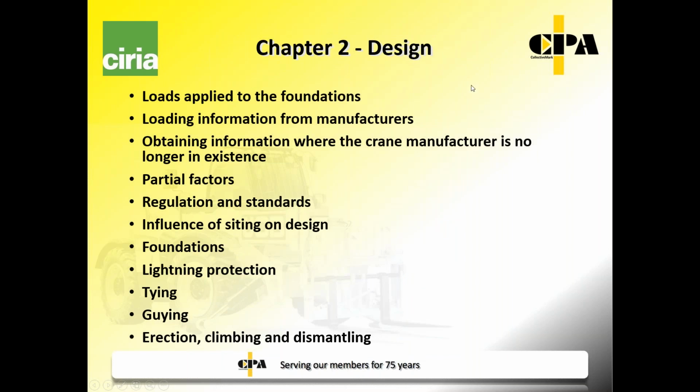And then moving on to chapter 2, we talk about the loads applied to the foundations, loading information from manufacturers, how to obtain information where the crane manufacturer is no longer in existence, which for old cranes is often quite a problem. We talk about the partial factors that are used in calculations. We talk about the regulations and standards, the influence of siting on design. I'll say a bit more about that in a moment.